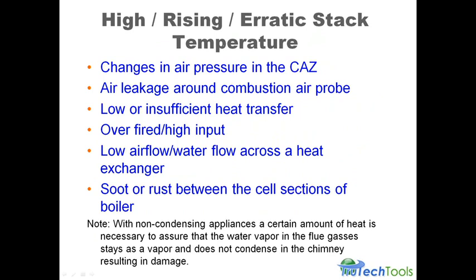Air leakage around your combustion air probes is another problem I see. When people find these erratic stack temperatures, a lot of times it's because they're not testing properly too. There's a cone that comes with your combustion analyzer that, if the hole is bigger than the probe, you need to screw in so that you don't suck air around the analyzer shaft itself.